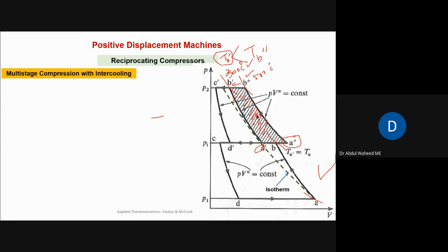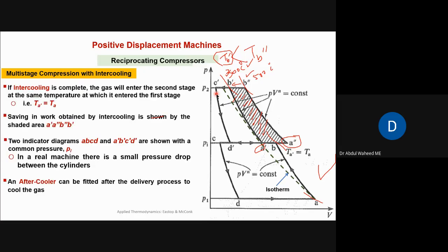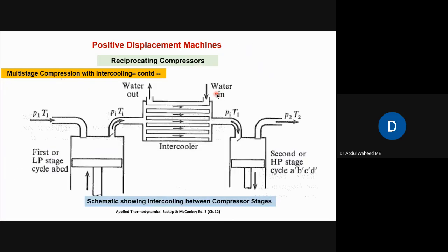If there are questions, ask. The link of this topic is also with your last chapter, Chapter 4, where in some cases 3 compressors are also used with intercooling. Here we have discussed 2-stage compression with intercooling. There could be 3-stage compression, where again it enters, then is intercooled, so you can further reduce the work input. But with all this, yes, hopefully it is clear.